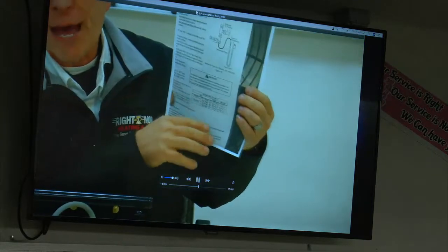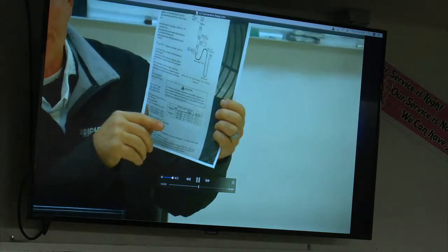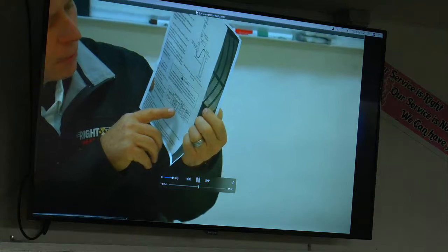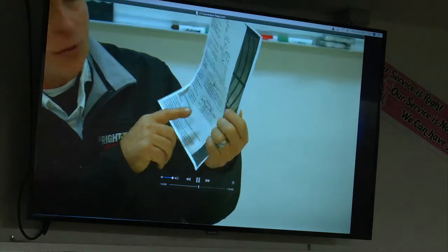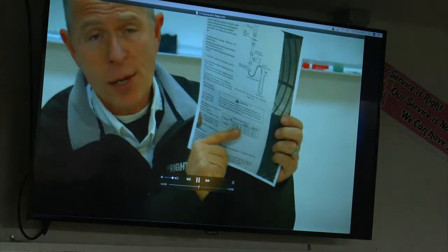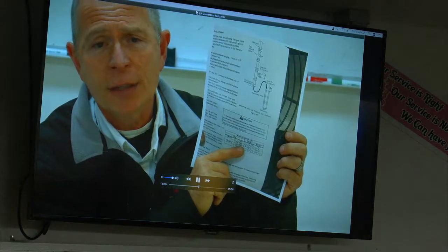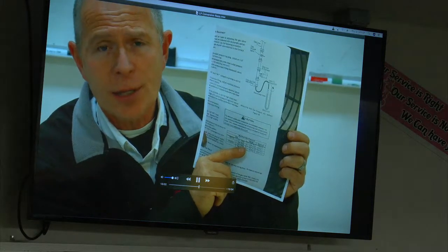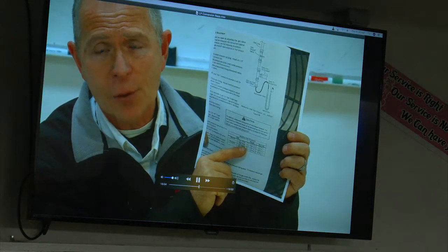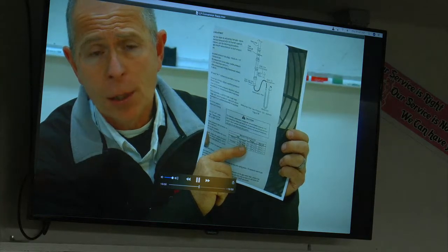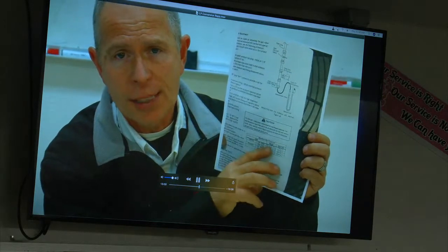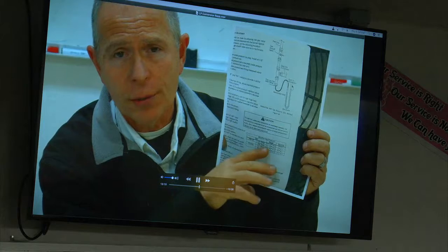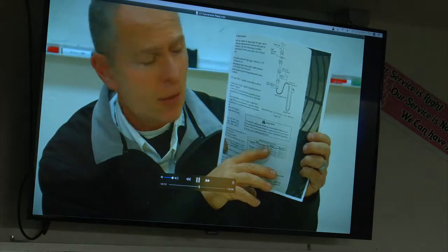In the middle of that is what they call the nominal, okay? You can adjust, but try your very best not to go below the lowest point setting. You may have intermittent ignition issues where there's not enough gas for it to burn off properly, which will come to the temperature rise section a little later on when you're finishing that.